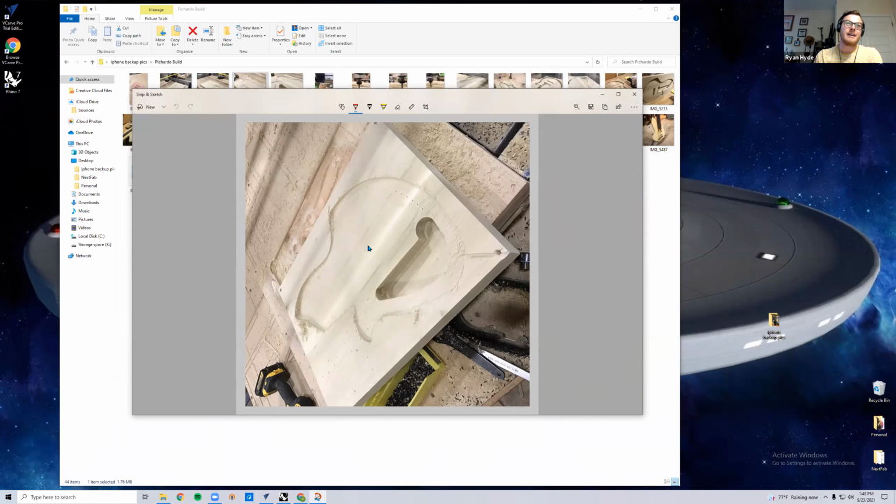Here I've milled the pocket, the cavity for the base, and I've milled the whole back of the base. And what you can sort of see in the background over here is that I have a whole platen piece of wood on here that I carved out a rectangle that fits this piece of wood exactly. And so basically I can take this wood and flip it around in that pocket, and the goal is to keep my registration. And it worked really well. I would develop a different system in the future.